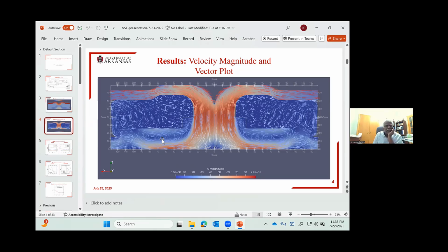And in this case, we are using OpenFOAM and non-orthogonal, most probably brick element type. The grid system is used, and very sophisticated multi-level grids are used. I don't have the plots of the grid, but you have to do a lot of thinking about how much refinement needs to be there, and in different places, what kind of levels of grid and spacing should be there.